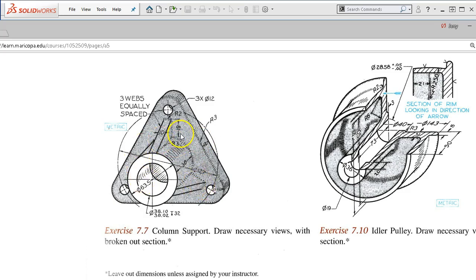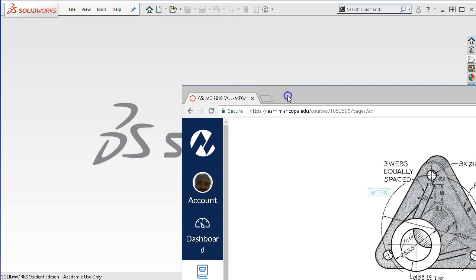And then we'll look at some of the different manufacturing processes, since this is more than likely a casting. Whatever this is supporting, we would want to look at possibly some different geometries, maybe a little more taper, maybe not as thick, some different types of reliefs to improve the manufacturability. So let's go ahead and open up a sketch on the front plane.